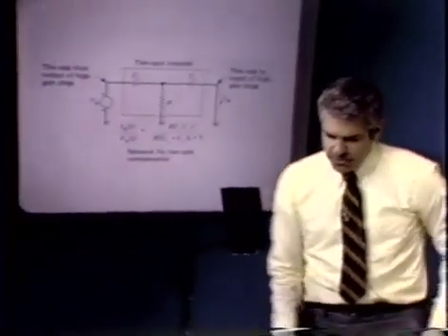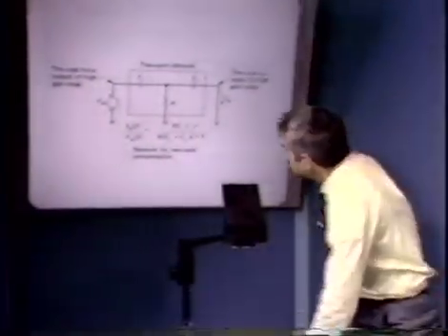In this case, we really have to use a two-port network in order to achieve our desired short-circuit transfer admittance. We want to get a short-circuit transfer admittance of the form some constant times s squared over tau s plus 1. We can't do that with a single element, as we did in the case of one-pole compensation, where we wanted a short-circuit transfer admittance just proportional to s. We can, however, get the desired form out of a T network as shown.